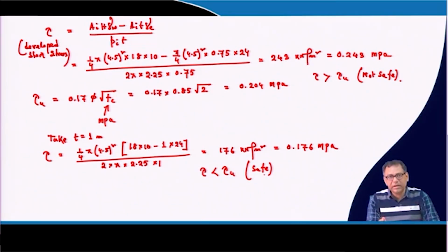So, here initially by calculation it was coming 0.75 meter, but when we did the checking for buoyancy it was fine, but for the shear checking it was not safe. So, we have to increase it, and we have now provided 1 meter. Now, all the conditions are satisfied. So, we will provide 1 meter thick concrete seal or bottom seal for this particular case.